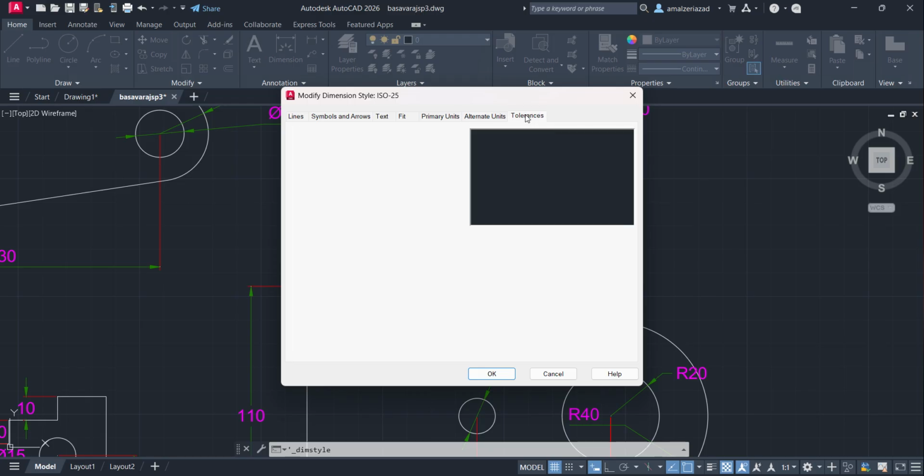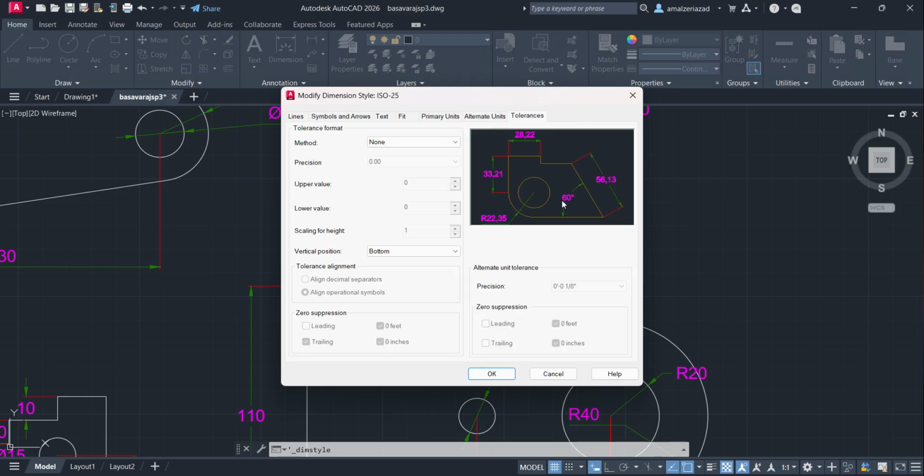And then we have something very important, which is tolerance. The tolerance is the upper and lower limit of an acceptable error. As a human being, or even with machines, the error is one which we can't avoid, right? It does happen. But still, with respect to a requirement, how much can you accept?